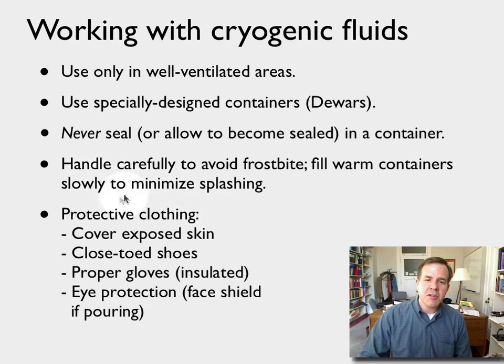Whenever we're working with cryogenic fluids, we want to use the proper personal protective equipment. So we want to cover exposed skin. An ordinary lab coat or shirt or pants is fine. Closed-toed shoes, as always in the lab, because cryogenic fluids commonly spill onto the floor and can spill onto our toes. We want to wear proper gloves.